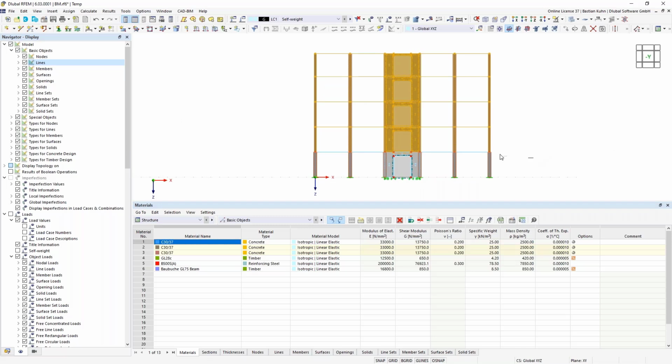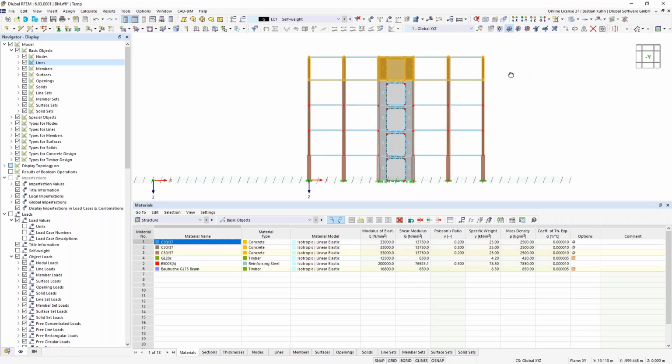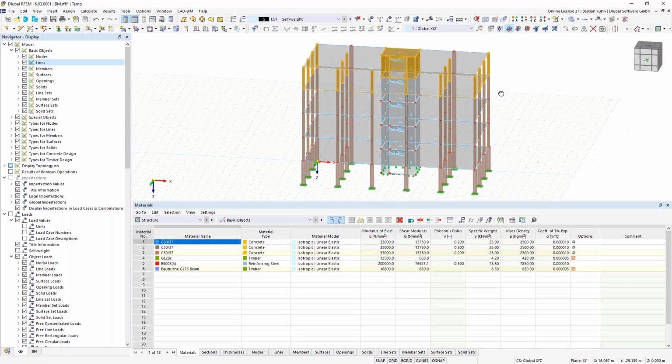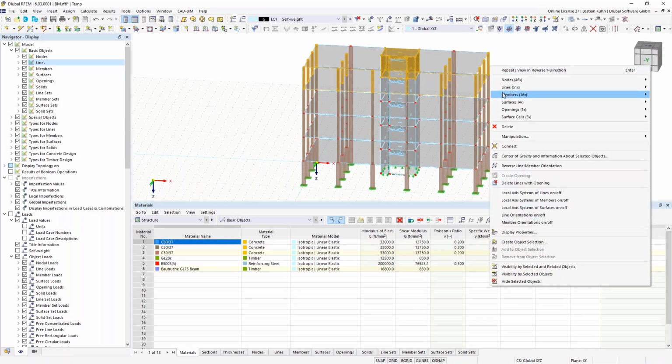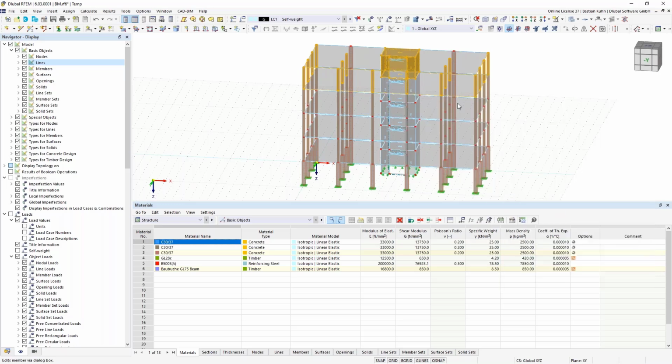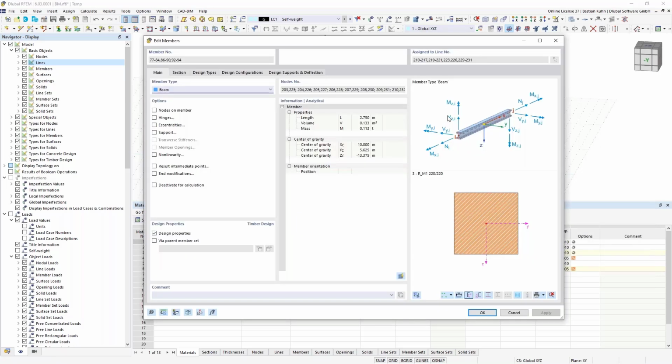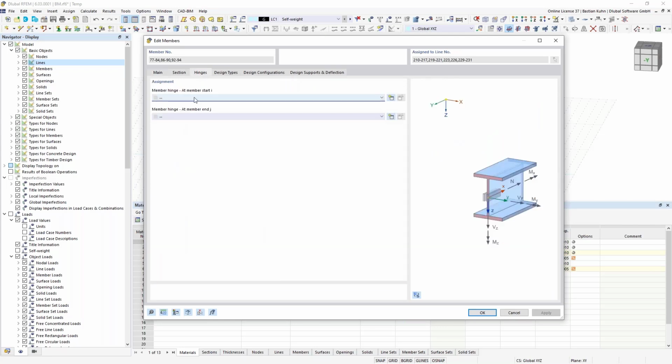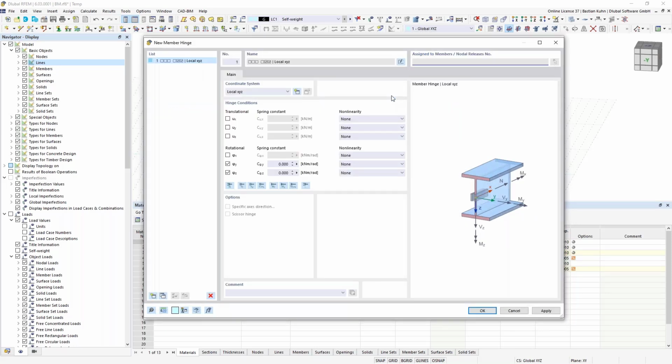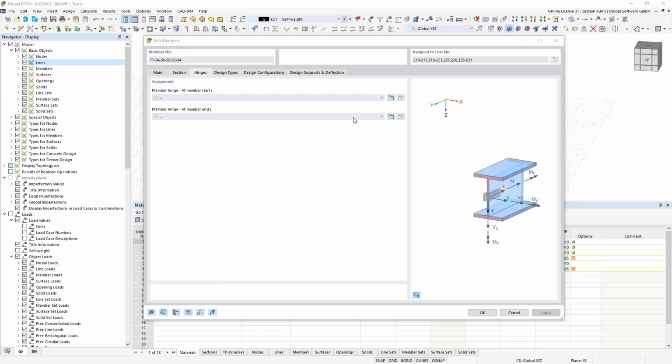Okay, this, and then these columns here, they should have hinges. I'm explaining afterwards why I only assign hinges in those stories after I have assigned or defined the building model data of it. All right, so that's UX, and we do the same for top and bottom.